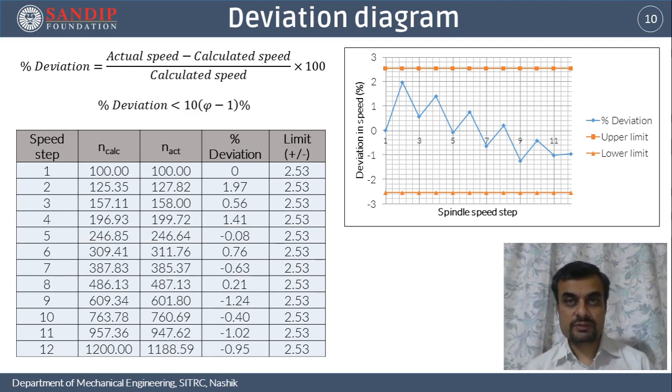If the rounding error is very high, something like 0.4, 0.5 or 0.6, then you should assume a higher number of teeth on the smaller gear and recalculate the number of teeth on the other gear in the same gear pair, so as to bring this rounding error to a minimum, because the rounding error gives rise to the variation in the number of teeth.